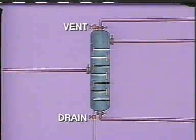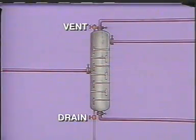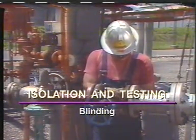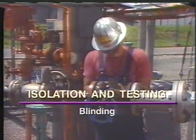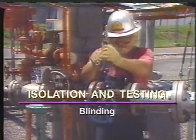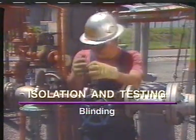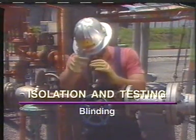If a tower is completely flooded with water, there will be no gas or oil left in the column. In order to drain the water, we vent the tower to the atmosphere. This prevents a vacuum from occurring above the liquid level while allowing the liquid to flow out the bottom. When a column is vented to the atmosphere, there is a possibility that hydrocarbon vapors from other parts of the unit will enter the tower and form an explosive mixture. To prevent this from happening, metal plates or blinds are placed in all tower inlet and outlet lines. Blinding a tower effectively isolates it from hydrocarbons that are present in other parts of the system.